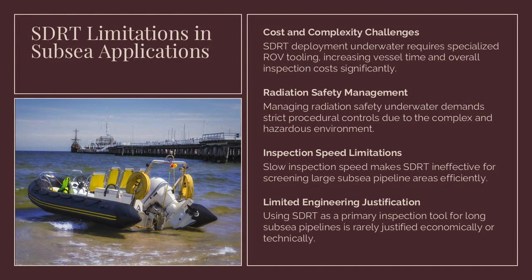The primary limitations of SDRT in subsea environments are cost, complexity, and safety. Radiation safety management underwater is challenging and requires strict procedural controls. Deployment typically involves specialized ROV tooling, increasing vessel time and inspection cost. Inspection speed is slow, making SDRT unsuitable for large area screening. We should note that using SDRT as a primary inspection tool for long subsea pipelines is rarely justified from an engineering or